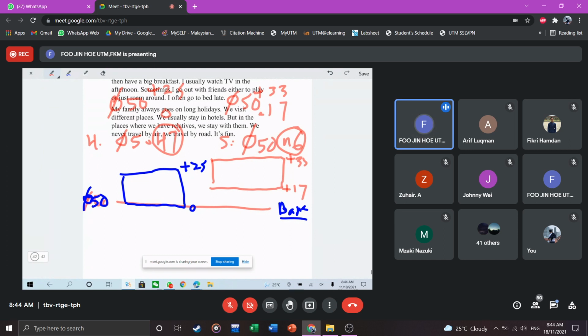If you can see, when this shaft at this size, plus 17, enters here, it means that it is still loose. And the minimum size of the hole will be 0. Okay, so if this plus 17 is going to go into plus 25, it will have a gap here. This gap will always ensure, or this particular gap basically tells you, that this thing is loose. You have a smaller shaft entering a bigger hole. All right. So if I enlarge this,